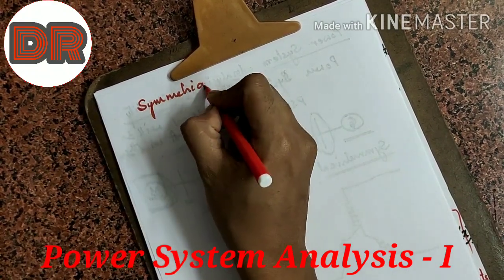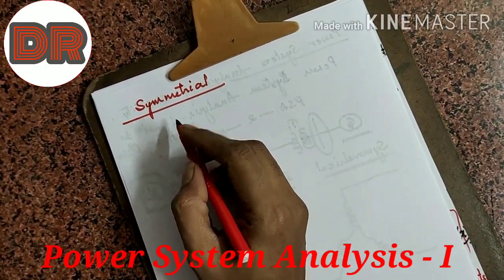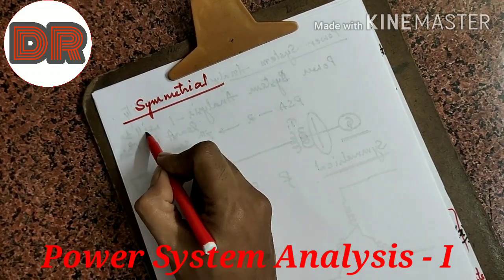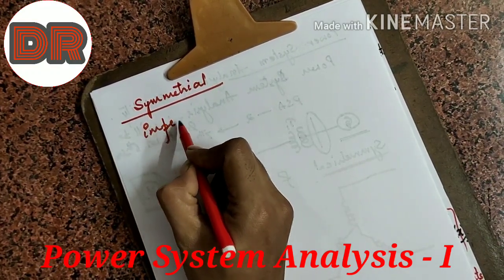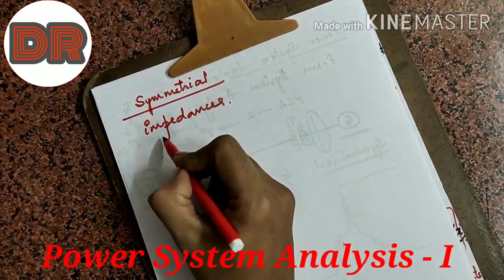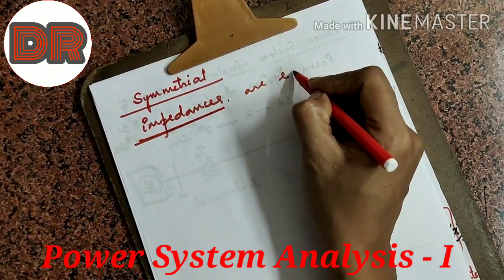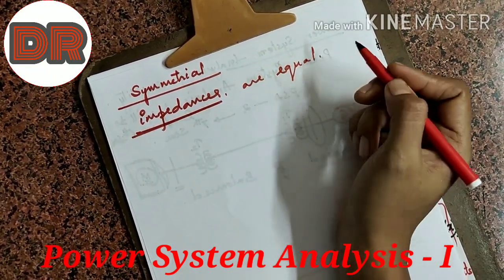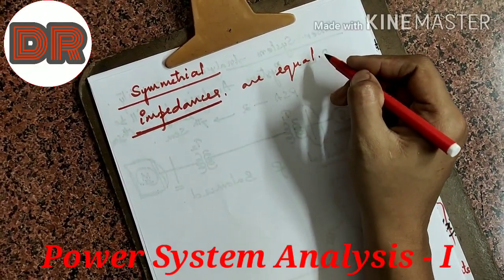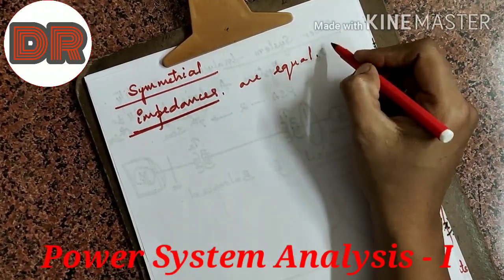The term symmetrical tells you that when we see a network or power system from any phase, the impedance value must be the same. Or in other words, if the impedance values of all the three phases are equal, then we can call such a system a symmetrical system or symmetrical network. Or if there is any mutual impedance, the value of mutual impedances also must be equal.